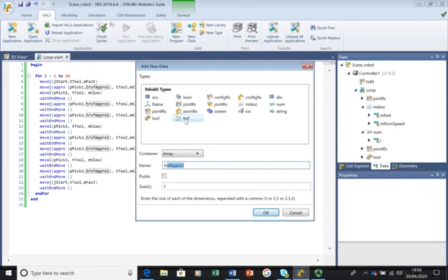And this is a translation. It's when the robot comes and it's hovering over our little object we're going to pick up. You don't want it to go straight there. Imagine you're picking up a cup of coffee and you're a robot, and you go and grab the cup of coffee halfway through the height of the mug. Imagine you've got a claw-like hand, you would knock the mug over. What you need to do is go above the cup of coffee and then drop down on it and grab.